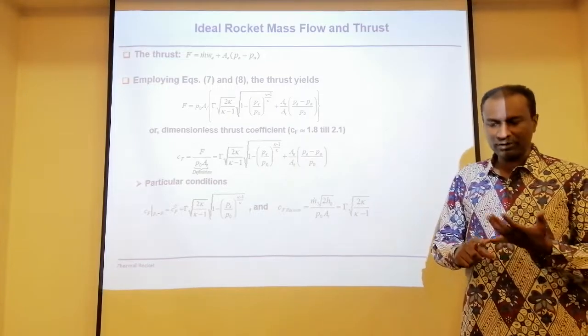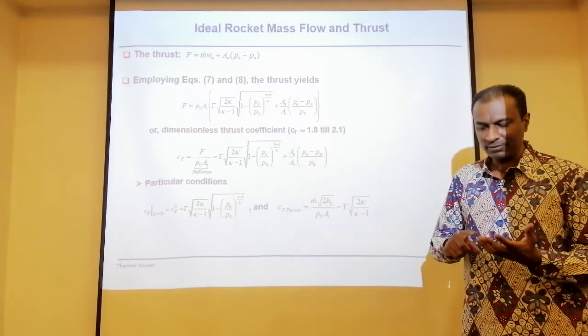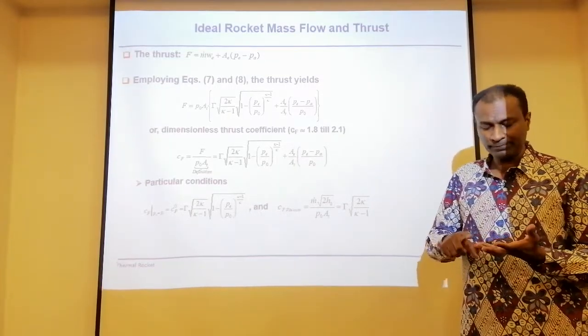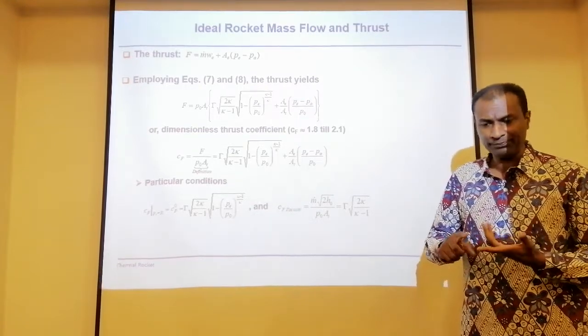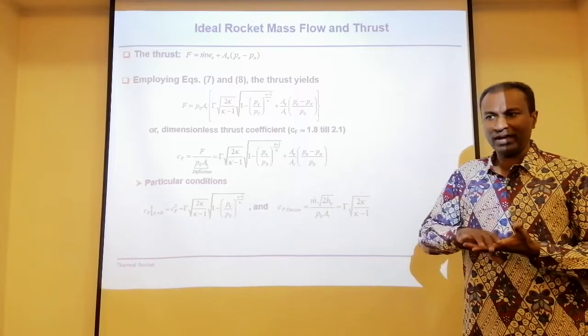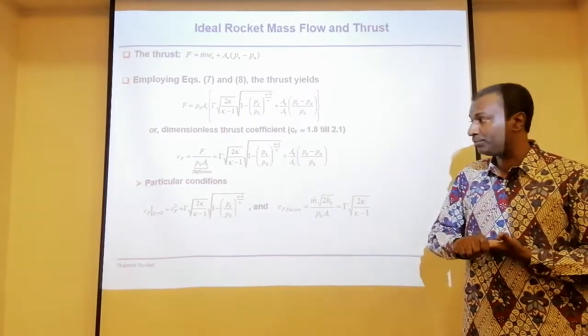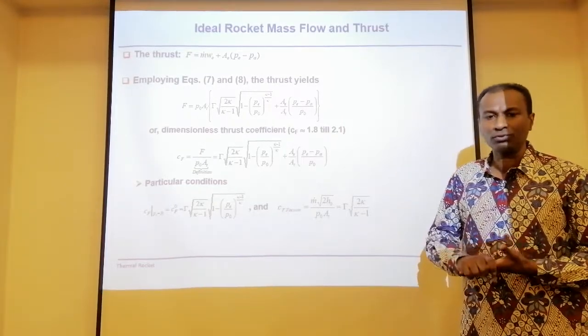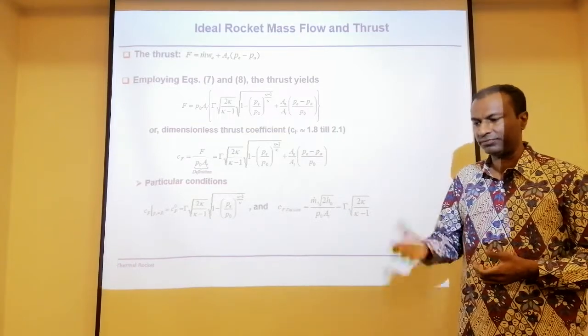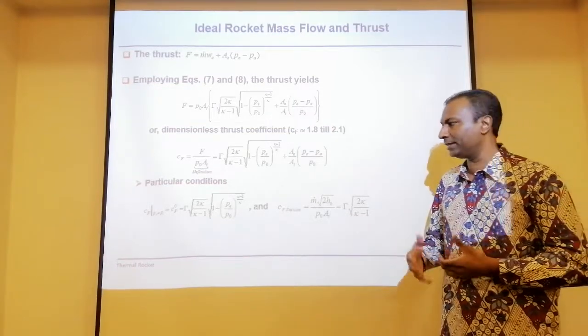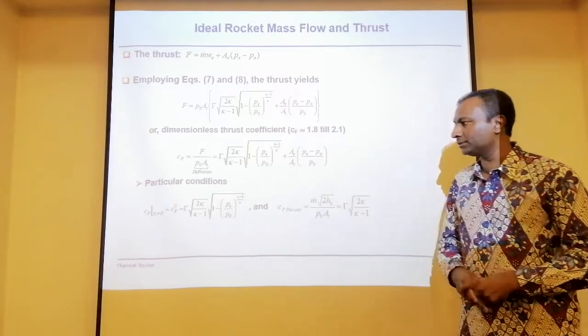Now, importantly, don't forget, the idea is that we need to calculate the pressure ratio, the temperature ratio, the density ratio, the surface ratio. When you have all this, you should be able to churn out all those important parameters for a rocket engine: the thrust, in fact, and the effective exit velocity. Alright, go on.